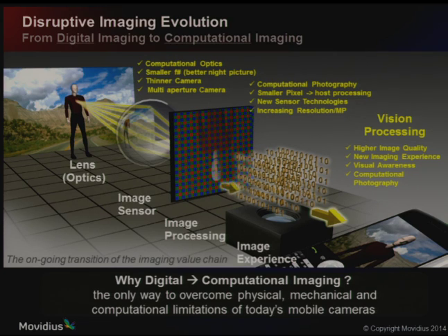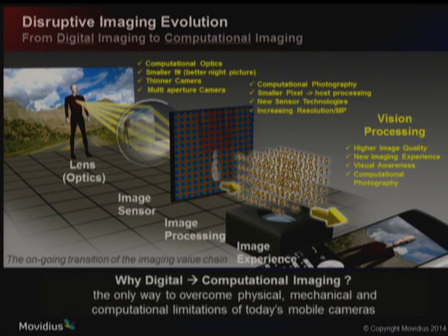There's also big change in terms of the actual 2D planar sensors themselves. Bayer CFAs have dominated for many years, and we're now moving to things like RGB-NIR or RGB-clear, where, for instance, you computationally reconstruct the green channel. In many devices like Myriad or Project Tango, you will find that there is more than one sensor attached. So you might have a global shutter camera, a regular VGA sensor, or a regular high precision sensor, and let's say a depth sensor.